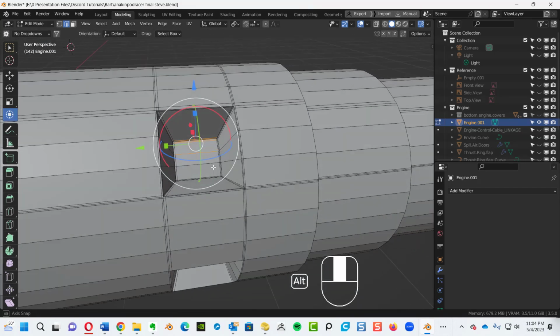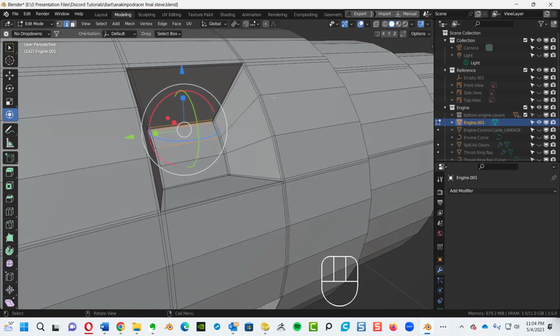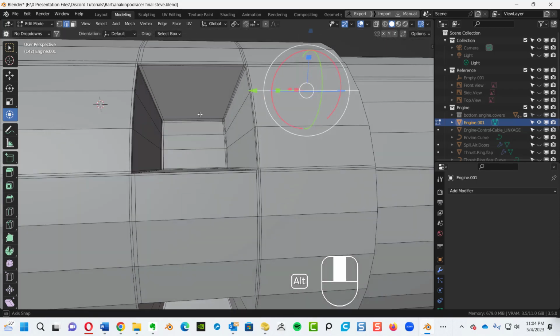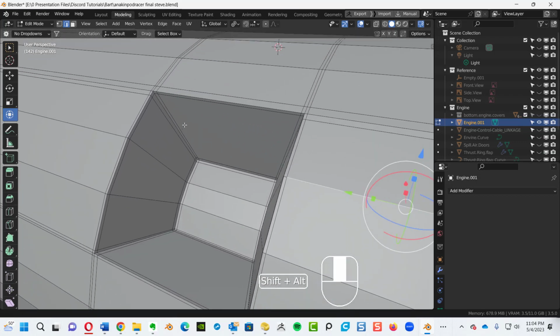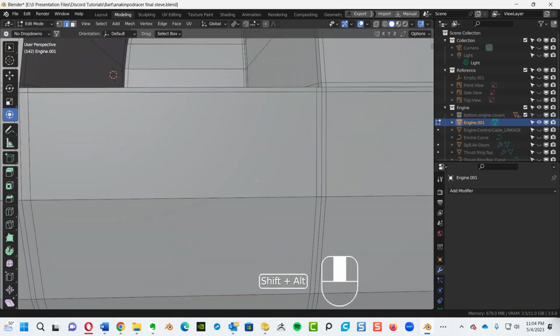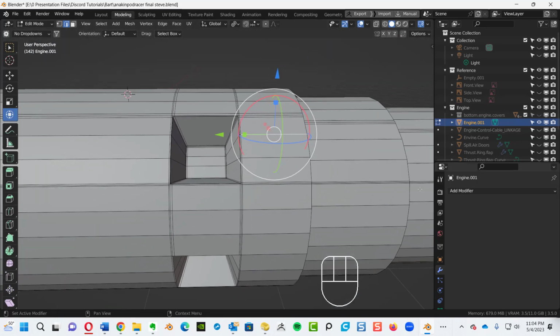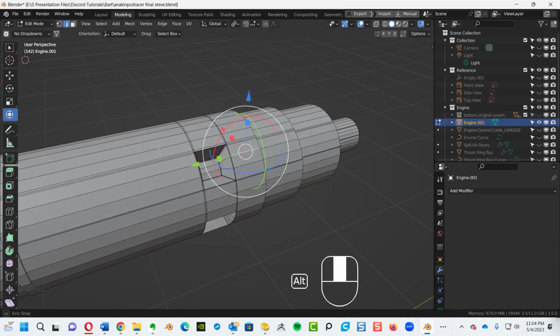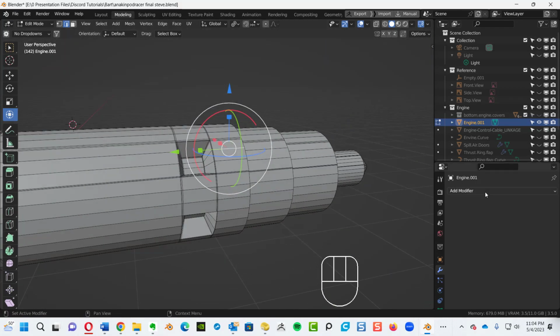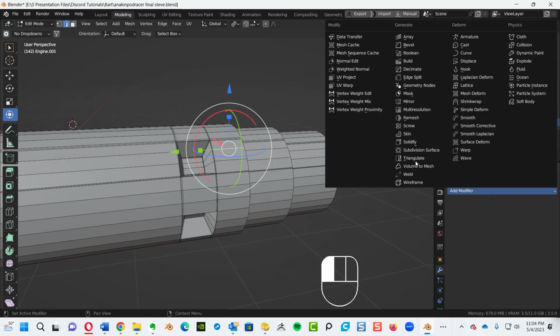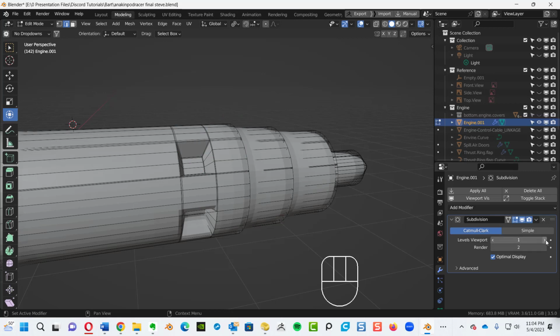So I just selected 3 of the poly faces and extruded them inward, right? As you can see here, I've also given some edge loops to lock down the edges of this rectangular piece, so that if I come over to my modifiers and add a modifier, let's say some subdivision surface to it, let's do so now. There we go. I'm going to give it 3 levels of view and 3 levels of render.